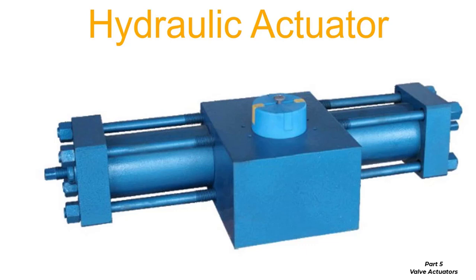But hydraulically actuated valves do have some downsides, such as the fact that you need to have hydraulic piping associated with the valves running all over the plant. You'll also need associated pumps, and there's a risk of contamination, which is far less than if you were using pneumatic valves, and an associated compressed air system.